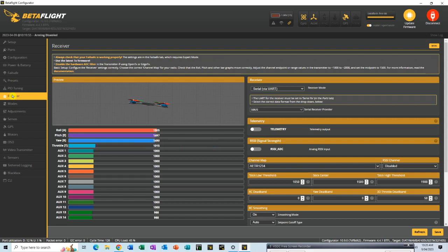That's what it is. The yaw, you can see the little quad at the top is yawing and doing everything. And if I want to have it rotate over that way and over that way, bring it back nice and flat. And if I want to roll the quad, I can roll the quad with these different settings. So we now know that everything is functioning as far as the quad is concerned. So we now have it set up to do the job of flying an airplane.